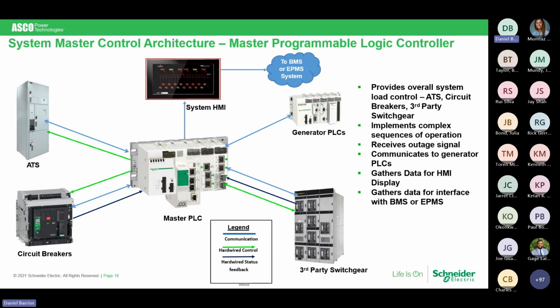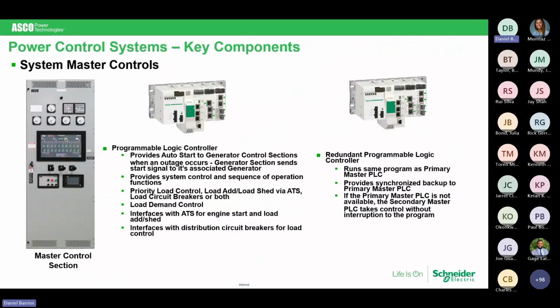The EPMS, the Emergency Power Management System. We would love to present that to you. It is not only how the system operates, but it is a means of monitoring everything so you can see what's going on. We can also, through some other avenues, give you control in some remote locations should you want to operate breakers. The system master can be, as I stated, the single or redundant PLCs, as you can see.